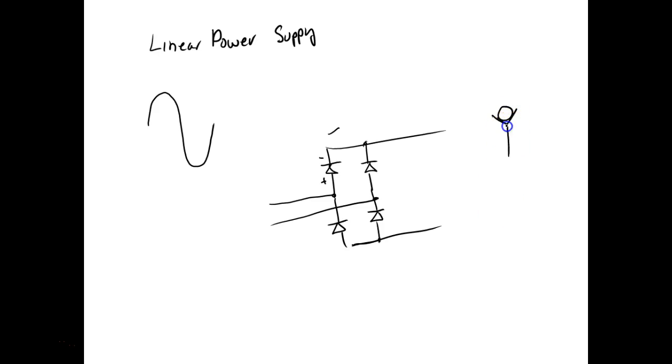So that's a check valve. That's the symbol of a check valve. What happens is when the fluid flows this way, the valve opens up, right? And you can see these things. But if it tries to flow this way, then the ball seat's inside the V and it blocks it. So that's on our directional control valves. Not our directional control, our flow control. So it allows us to meter the exhaust instead of metering the pressure.